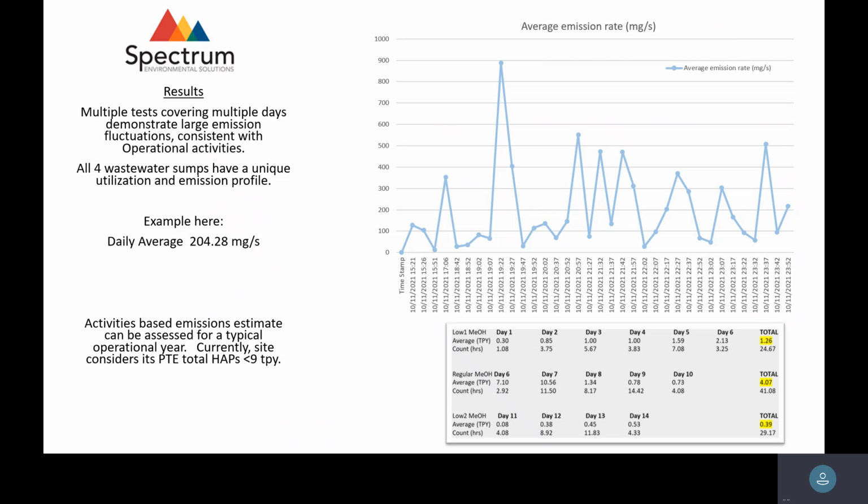The boiler blowdown is a little warm. So that water hits any one of these pits, that boiler blowdown water is going to do what to whatever volatiles may be in the water? All of it's gone. So redirecting, maybe cooling, maybe putting the boiler blowdown in a separate pit, letting it cool down, and then letting it flow into the city discharge pit. All of those little operational things are very insightful, very fun things to talk about, and engineers, at least I do, I enjoy hitting on all those operational improvements to help them manage their emissions in a much better way.